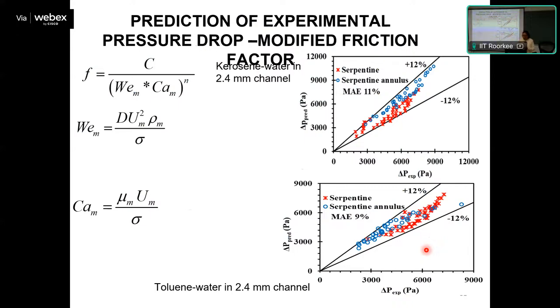So it is not a function of Reynolds number alone, but of something more, where the surface tension, the interfacial tension, comes into the picture. In that way we have taken into account the Weber number, and it more or less fits the experimental observation.